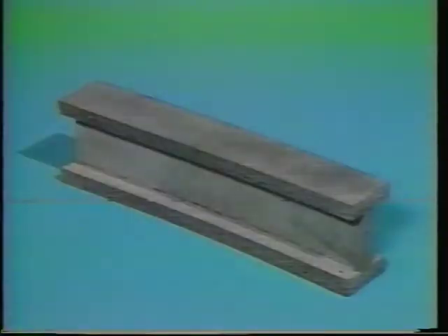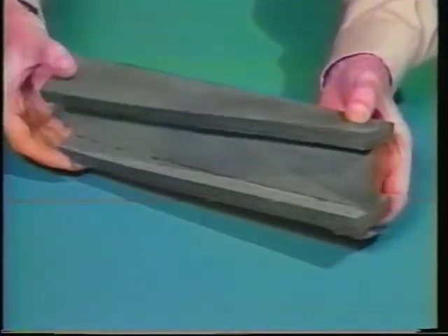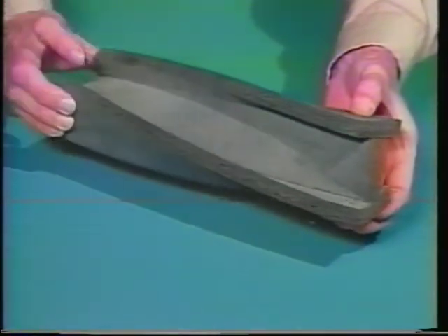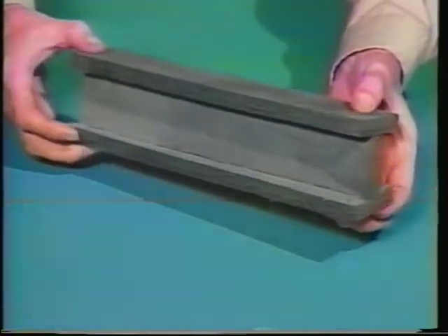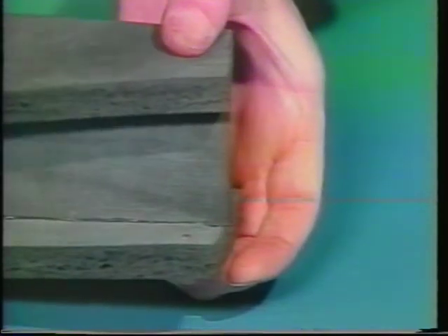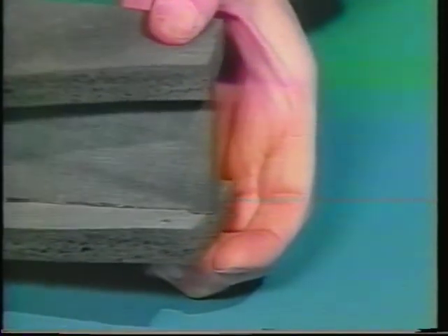There are other actions which are involved in the instability of beams. One of these is warping. For steel beams, actual warping deformations are very small and are barely visible, but they may be seen using the soft rubber model. This short beam is being subject to equal and opposite end couples, and torsion occurs. However, in addition to the primary twisting action, it can be seen that the end cross-sections no longer remain plane, but the elements of the cross-section distort out of the plane perpendicular to the longitudinal axis of the beam. This phenomenon is